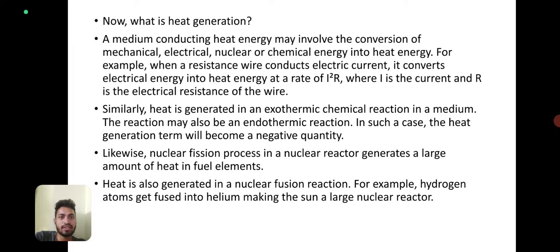Now, what is heat generation? A medium conducting heat energy may involve the conversion of mechanical, electrical or nuclear energy into heat energy. Similarly, heat is generated in an exothermic chemical reaction in a medium. The reaction may also be an endothermic reaction. In such a case, the heat generation term will become a negative quantity.